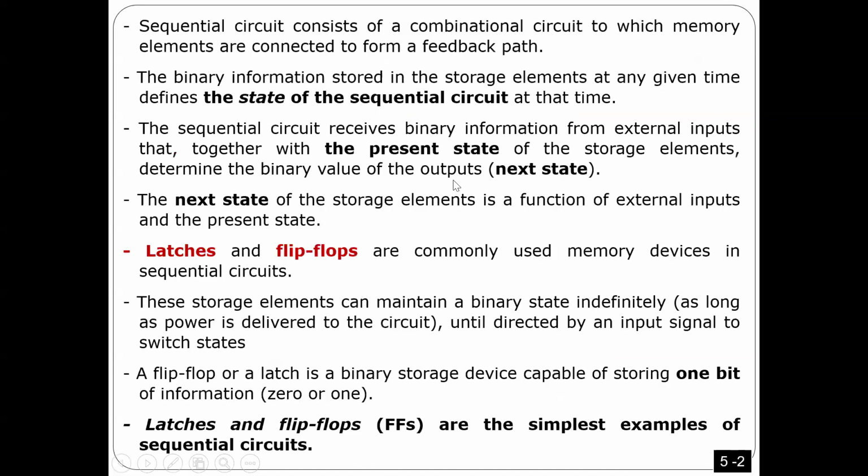In memory elements, it can only store 1 bit. But it's different. Don't think about your hard disk or memory stick or something like that. No, it is a logic circuit. If you have a flip-flop and it is storing 0, then as long as the power is connected, it is 0. Once you disconnect the power, it's going to lose the information. You understand what I'm saying? As long as the power is connected, it's going to store 0, unless you change it, because, as I will explain, there is a way to change this number.